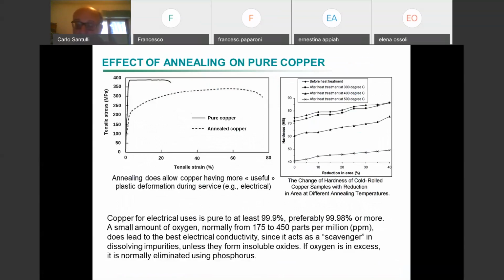From steel we pass to copper. Copper has got a long history, of course. With copper, you started from copper alloys, so bronze and brass. Brass is the alloy with copper mix. Although in commercial terms they are often all used and intended as bronze, in reality, if you stick to the right terms, not the commercial ones, the alloy with tin is bronze, the alloy with zinc is brass.